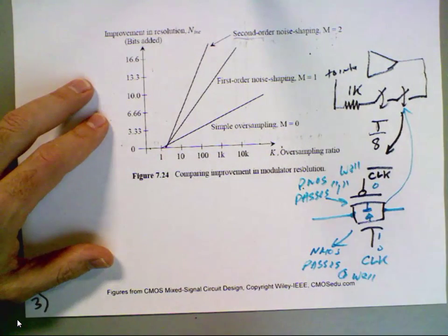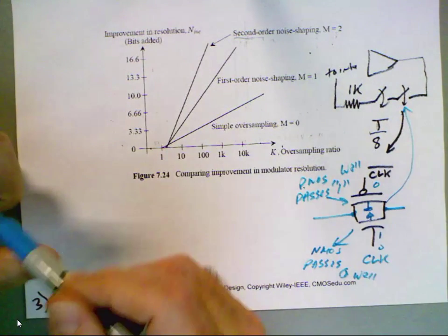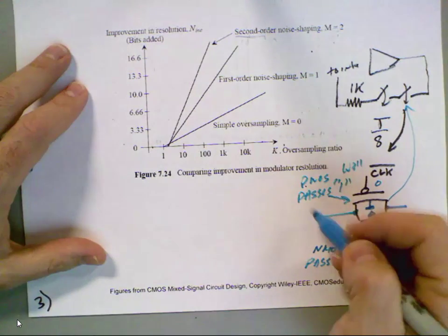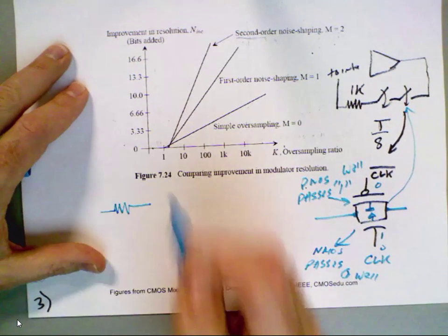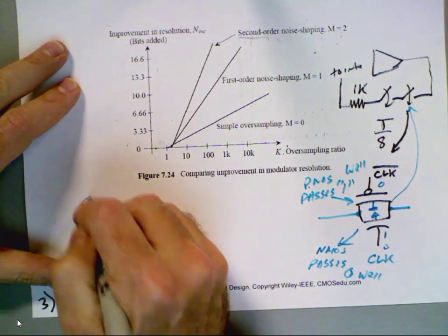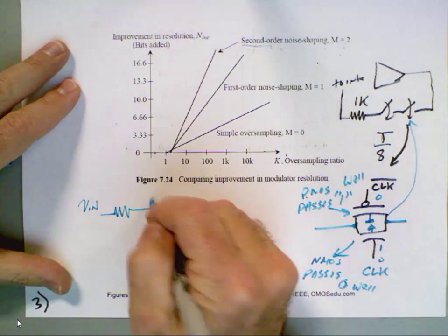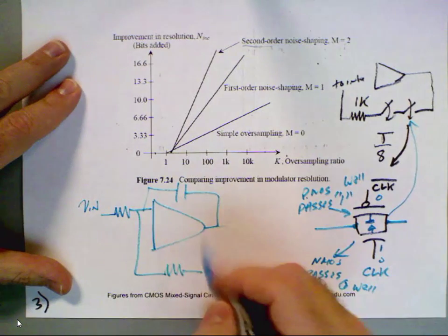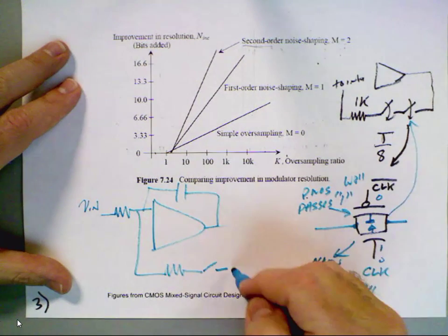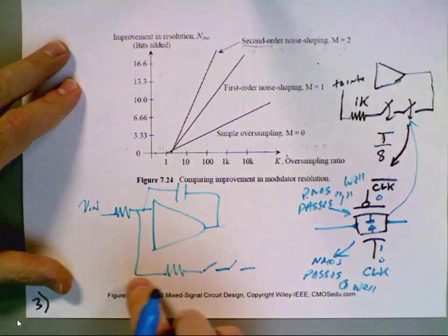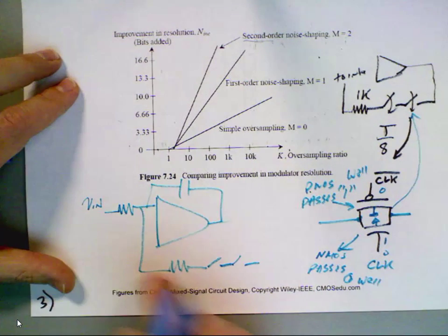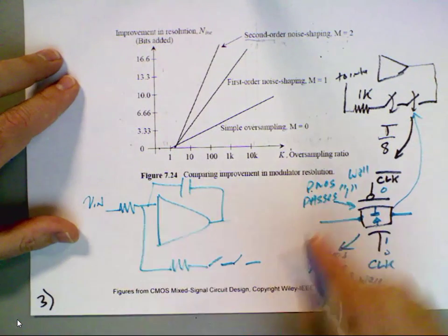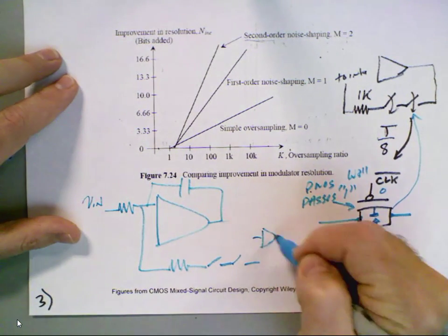Okay, so one other big issue here. These devices have some resistance. So I've got my resistor coming in to the integrator, so here's VN, and it goes into my integrator. I'll just draw it like this, and then you have a feedback, and you put a resistor here, and then you put your switches, these TGs, in series. It might work better to have them on this side, or one on each side. I don't know which way to put it in. I think it doesn't matter.